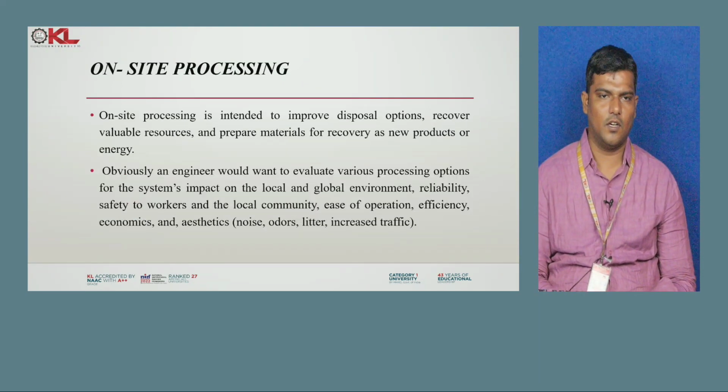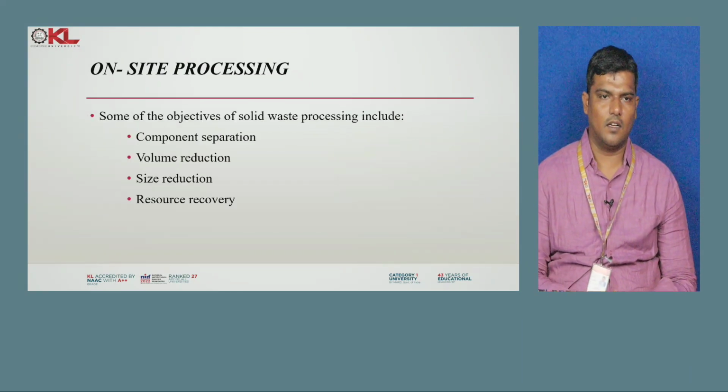Next, on-site processing is intended to improve the disposal options, recover valuable resources and prepare materials for recovery as new products or energy. Obviously, an engineer would want to evaluate various processing options for their impact on the local and global environment, reliability, safety to workers and the local community, ease of operation, efficiency, economics and aesthetics. Some of the objectives of solid waste processing include component separation, volume reduction, size reduction as well as resource recovery.